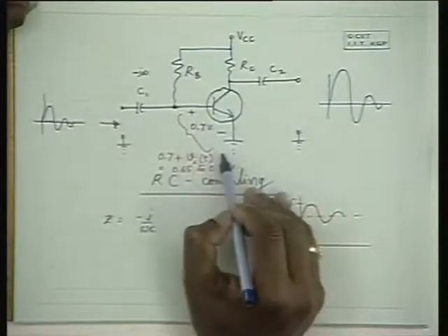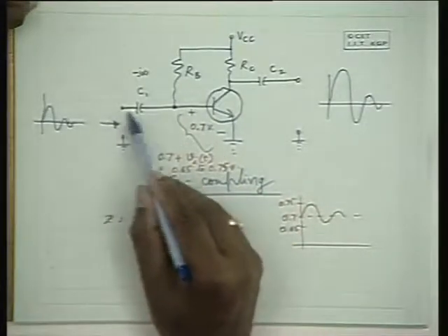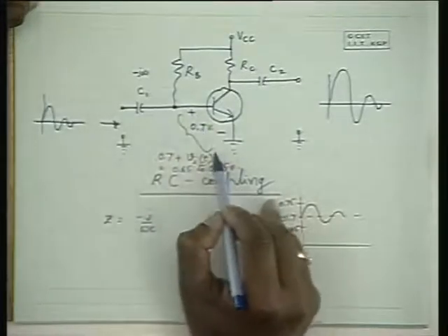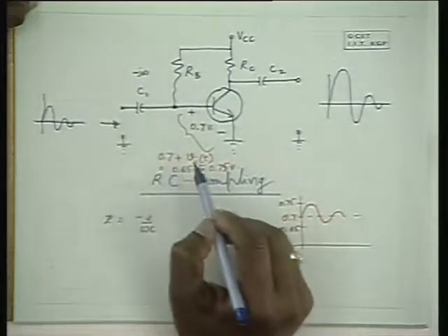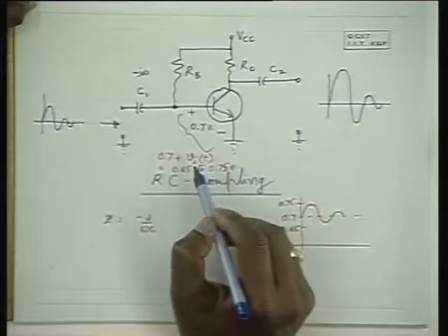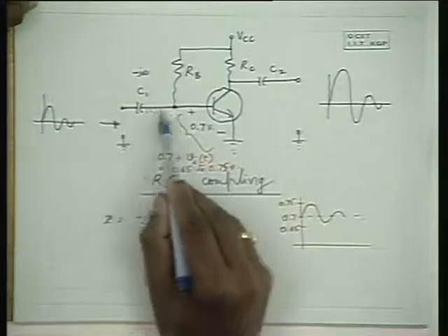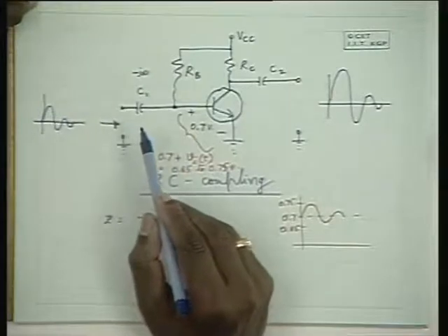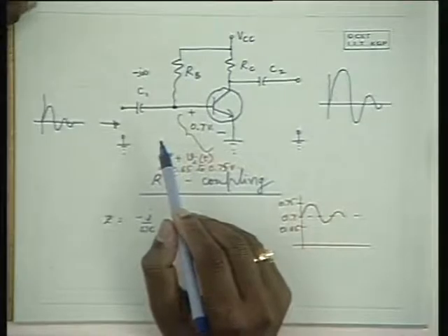It's only some load resistance. Therefore, this voltage divided by this resistance plus this impedance plus this impedance is the current, and that current flows in this direction. Conventionally we treat the current as going inside, but for an alternating signal, current going in one direction has no meaning except for conventional purposes.